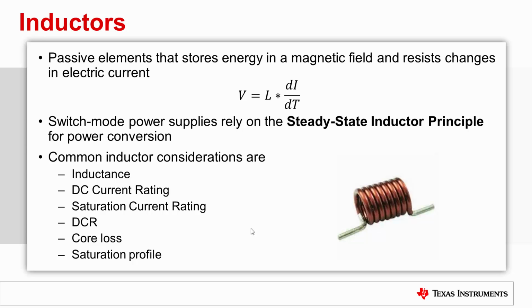This is a tricky specification because inductors pass triangular wave currents, so the peaks need to be kept within the saturation current limit. If the saturation current is exceeded, the inductance will approach zero, causing the inductor to act like a short circuit. DCR is the DC resistance, which factors into the DC current rating. This number will allow the designer to calculate the DC losses in the inductor.